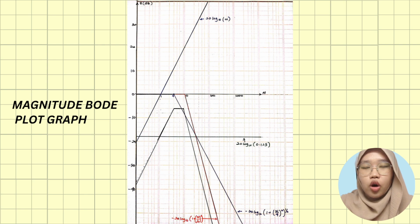Then, at ω = 10, we hit a double pole, where each pole contributes negative 20 dB per decade. The double pole results in a slope of negative 40 dB per decade. After this point, the gain drops off quickly as the frequency continues to increase. Also, the constant in the transfer function, which is 0.125, shifts the entire magnitude plot downward by about negative 18 dB, calculated using 20 log 10 of 0.125.